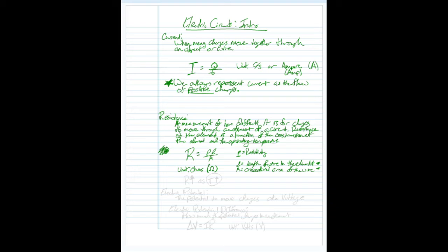Now, I also said that it's a factor of the operating temperature. We're not going to look at an equation for this. We just need to know that resistance will increase as temperature increases. This might be counterintuitive because temperature is speed of particles, and if the particles are moving faster, then surely the current should move faster. But in reality, this temperature is the random motion of particles. If we have particles moving around randomly in our wire, faster and faster and faster, it's going to be harder for our electrons to move through it smoothly.